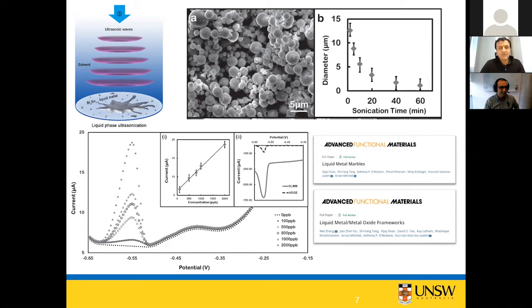Here, we introduced a sensor that with voltammetry, you can swallow, for instance, lead and cadmium into this liquid metal and spit them out, and then measure the current. And current measurement gives you the intensity; the concentration of the heavy metal ion in the environment is proportional to this current. Basically, it's a heavy metal detector. Actually, it has been commercialized. This is a paper from 6-7 years ago, and now it has been deployed to many water reserves around the world. Very highly sensitive.